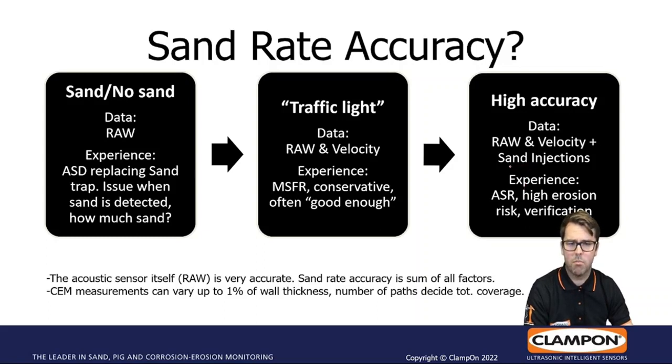It's always important also to say that sand injection is done also to do a verification of your system to make sure that it actually works, because we have seen systems where you are producing on too low velocity, too small particles, maybe viscosity in the liquid, and you think you have an ASD system which works, but the sum of these factors cause that the particles are not detected. So the instrument itself, the ASD, is an acoustic sensor, which is very accurate. What I'm talking about here is the accuracy for the sand rate.